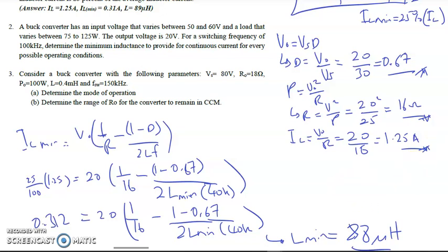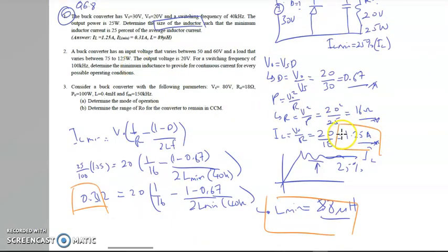When we use the inductor, the minimum inductor current, when we use this value of 0.88 microhenry, will go down to 25% of I L average. So all the values are obtained: the I average, I minimum, and the inductor value for the converter.